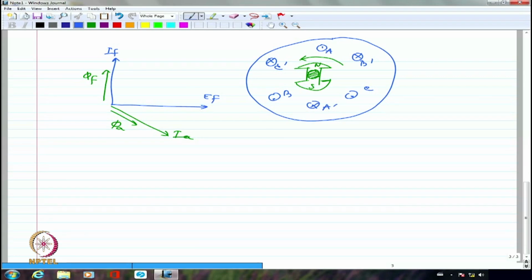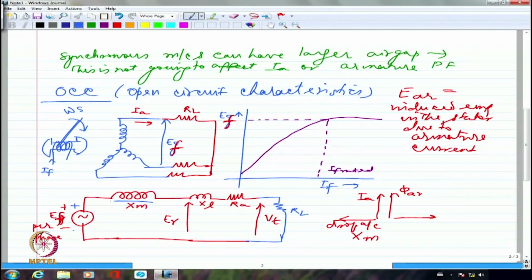It is not possible to bring it over to infinity. So Lenz's law very clearly says this has to be in the opposite. So if I actually show it in the equivalent circuit, if this is plus and this is minus, I have to show this as this plus and this is minus. Clear? So that is how we get this overall terminal voltage.